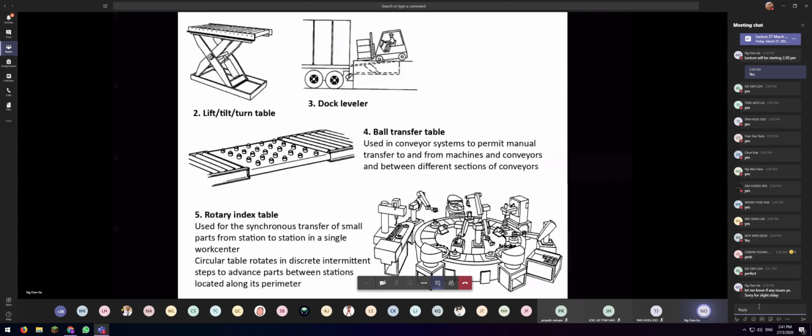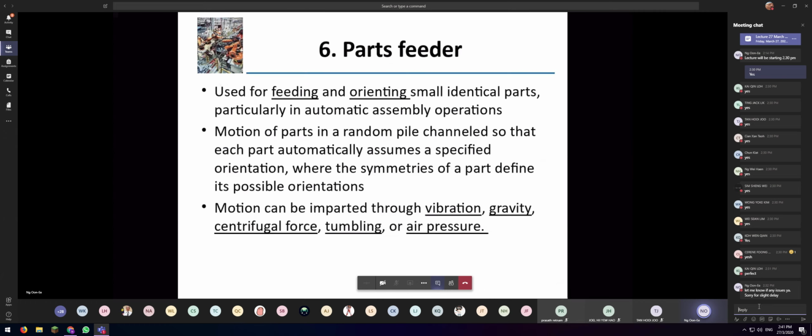So normally it's just going along the conveyor. When it reaches this part, you can easily move it off in a perpendicular direction. Your rotary index tables, you can see down here, each item is on a discrete panel, and it will move to the next discrete panel. And so you will position your processing equipment, your robots or whatever it is, above a particular discrete panel. So then the item will move, and that's how it is being positioned.